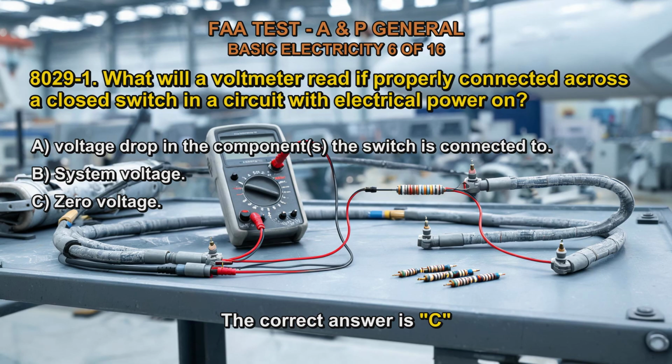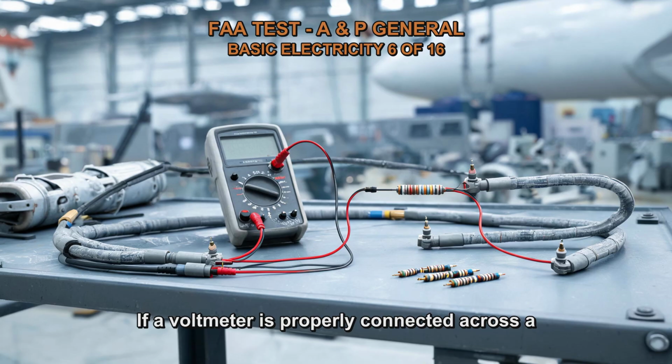The correct answer is C. If a voltmeter is properly connected across a closed switch in a circuit with electrical power on, it will read zero voltage. When the switch is closed, it creates a direct connection between the two terminals, so there is no voltage drop across the switch.